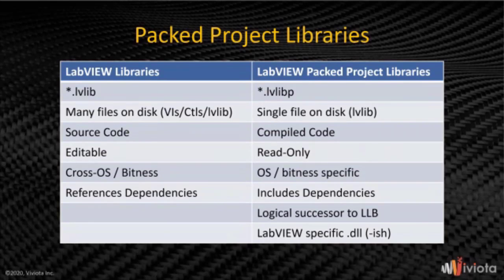So if you compile something for 2018, it will still work when called from LabVIEW 2018 and 2019 and 2020. In my own limited experience, I find that this works most of the time. Occasionally something changes and you will have issues and you'll have to recompile it for the new version of LabVIEW, but most of the time I found that it works well. It is 2017.